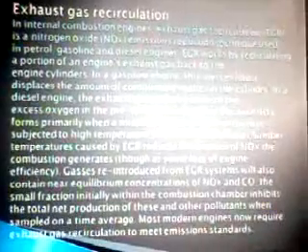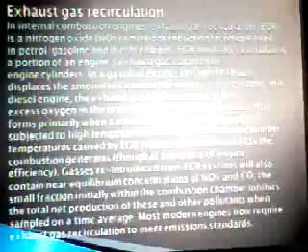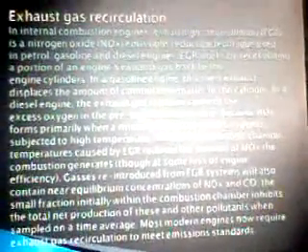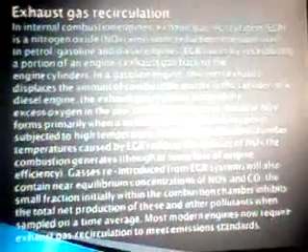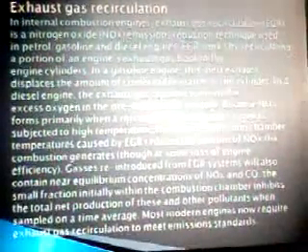In a diesel engine, the exhaust gas replaces some of the excess oxygen in the pre-combustion mixture, because NOx forms primarily when a mixture of nitrogen and oxygen is subjected to high temperature. The lower combustion chamber temperature caused by EGR reduces the amount of NOx the combustion generates, at some loss of engine efficiency.